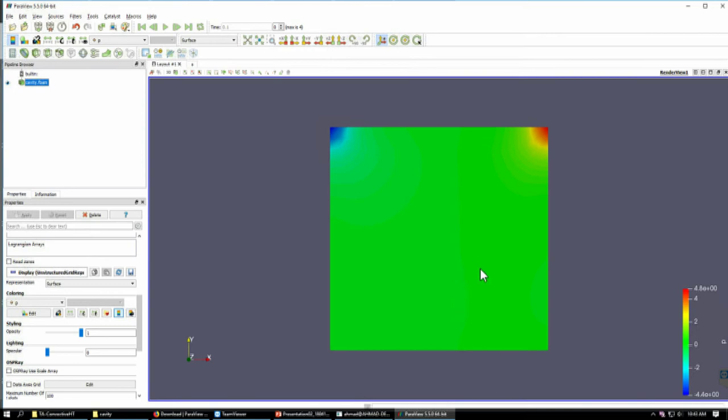Now, if you try to understand this physically, it makes sense, because what was our problem? Our problem is a cavity where the top lid is moving. So when the top lid is moving in one direction, what will happen? The pressure at the corners of this box will change. And how will the change occur? The pressure at one end of this box will increase, this one will decrease, because the plate is moving in this direction, and flow is getting diverted into this direction.